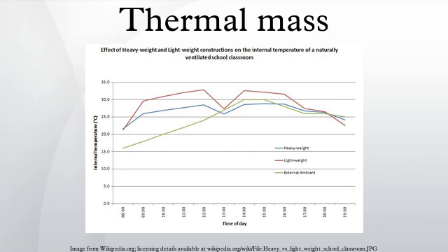Since the most important source of thermal energy is from the sun, the ratio of glazing to thermal mass is an important factor to consider. Various formulas have been devised to determine this. As a general rule, additional solar exposed thermal mass needs to be applied in a ratio from 6 to 8:1 for any area of sun-facing glazing above 7% of the total floor area.